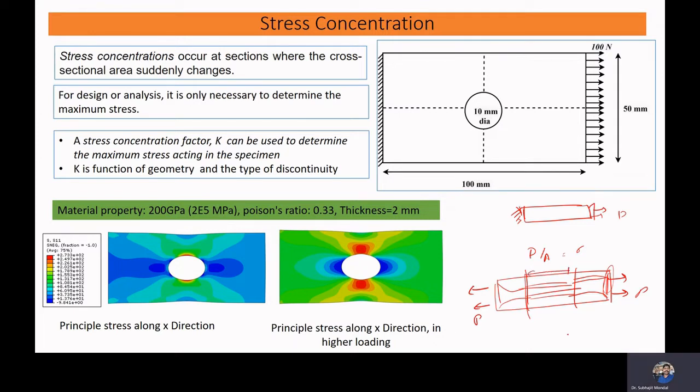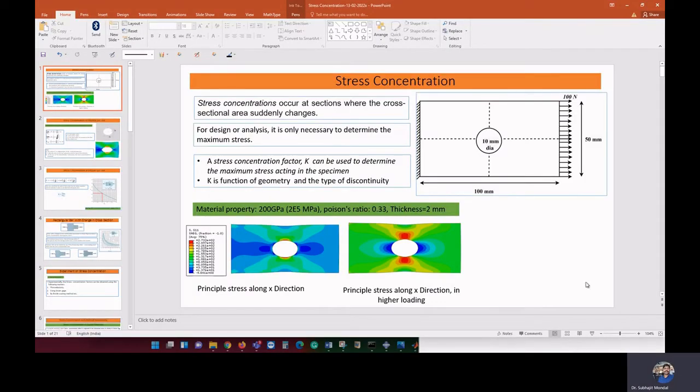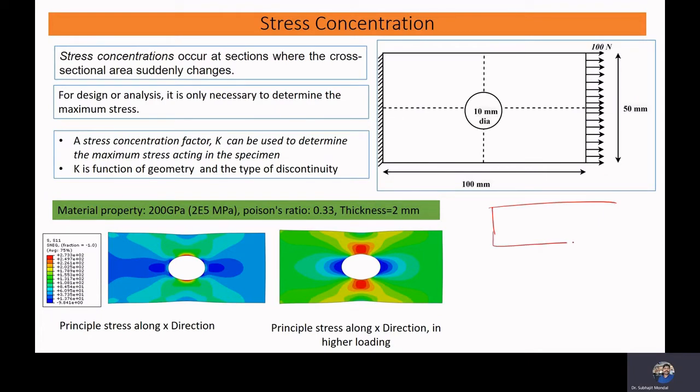Now, probably you can recall that while doing a tensile test, we used to measure our data. Why did we measure in this middle zone? Because in this zone, stress is uniform. In such cases, failure of the material occurs either in this middle zone or near the support. Many times there is failure near the support because stress is high here. In such cases, we reject the sample and consider those samples which failed in this zone, so that we make sure stress is uniform here, and whatever data we measure here comes from the uniform stress in this zone.